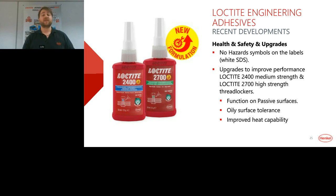The upgrades for these products mainly include increased strength and faster cure on passive new generation coatings such as zinc flake and branded Geomet fasteners. They are also offering better oil tolerance, which means they can be used on as-received fasteners, which is bringing them in line with the performance of products such as 243. They also offer improved resistance to thermal cycling.